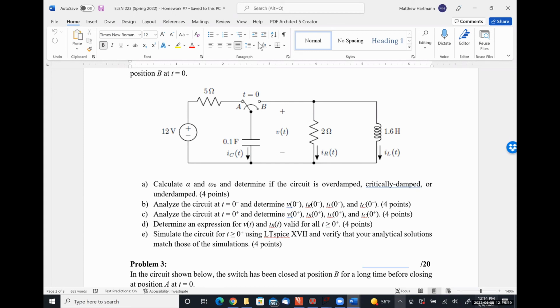Yeah, so in the series RLC circuits, it was always I times R because I was common to all of the elements. And in these parallel RLC circuits it's always going to be V over R because V is common to all of the elements. If I ask you for a resistor quantity in one of the general RLC circuits or the general second order circuits, then you'll have to do something else.